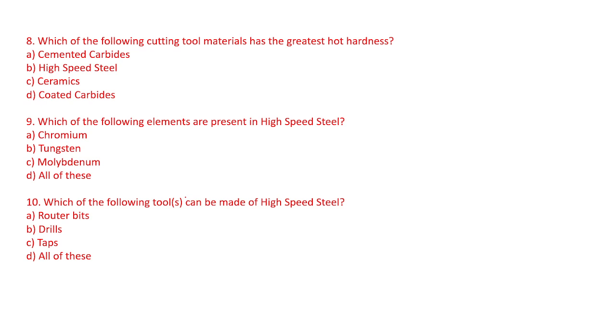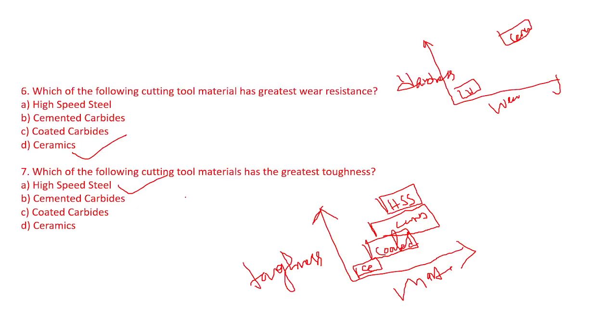And also there are ceramic cutting tools or cemented carbide. Ceramic cutting tools are constructed mainly from alumina, or Al2O3, and silicon nitride. They have also introduced the use of silicon carbide and ceramic matrix composites. We have seen from the plot itself that it exhibits excellent hardness, toughness, and thermal conductivity.